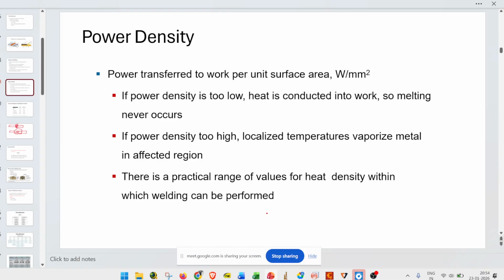If laser power is too high, once the material receives that laser energy as thermal energy, that power is enough to completely vaporize the surface layers. There is not enough time left for the top layer to transfer that heat to the layers below. So it immediately vaporizes, and that is also not desirable for welding. We just want the in between, so that the material will be melted and will become solidified after the cooling process.